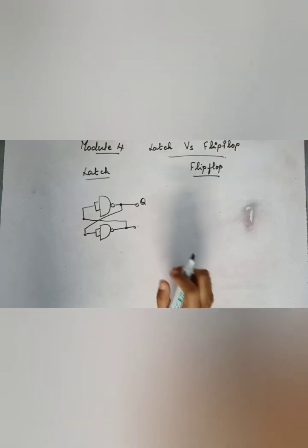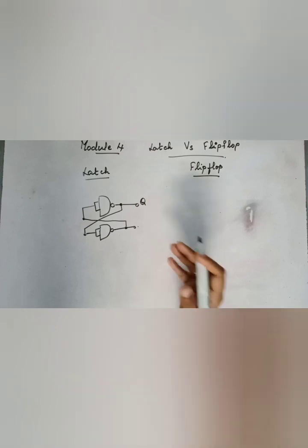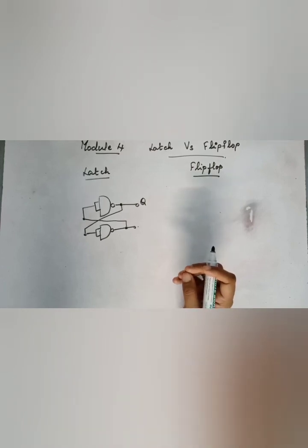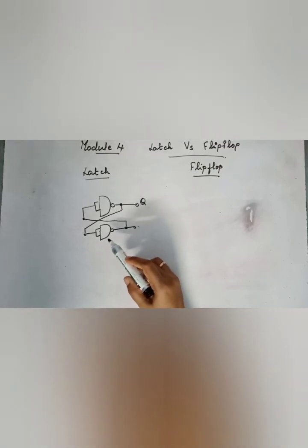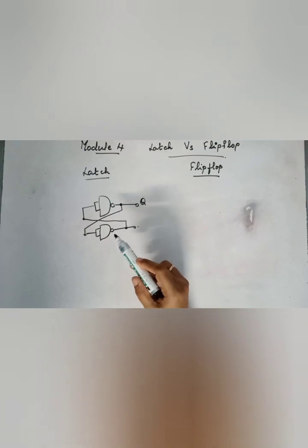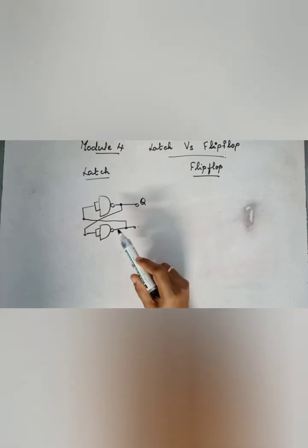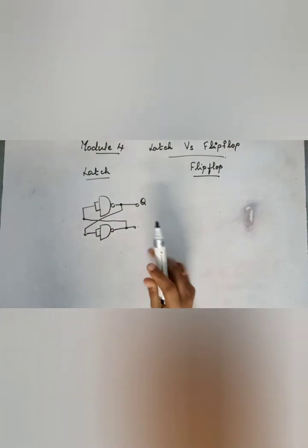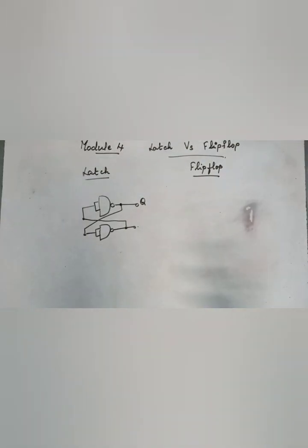Ground will be around 0.2 volt. Why do we need this VCC and ground? Because you have transistors inside the logic gates, and in order to turn on the transistors we need the voltage. So for that you have 5 volt. We are just switching on the circuit, that is, we are making the IC or the logic gate active by giving the voltage.